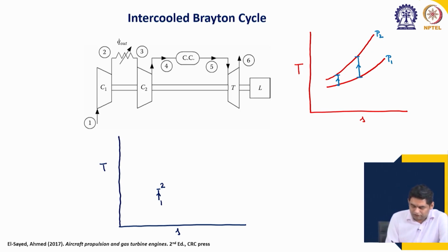So, this air after partial compression is again cooled back, such that we come back to the same temperature. It need not always be the same temperature; I will explain why I am saying we come back to the same temperature. This cooling is done by using a heat exchanger. The air is cooled, and this heat exchanger typically works by using water at ambient condition for cooling the air.